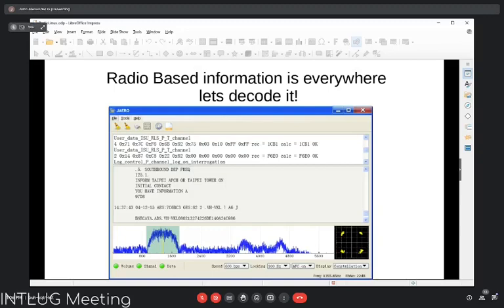Yeah. And there you go. And this is from another example. J-Aero will allow you to receive different bits of data of different modes. So if you look here, this is the actual bottom there. You'll see a band scope of the different channels within which the Inmarsat is transmitting. On the right hand side, you'll see a constellation, and that's the actual data coming down. It's there basically to allow you to get some idea of the quality of the data.